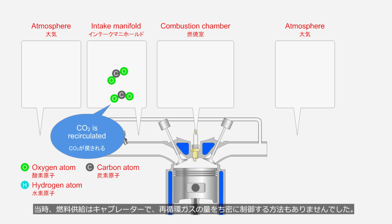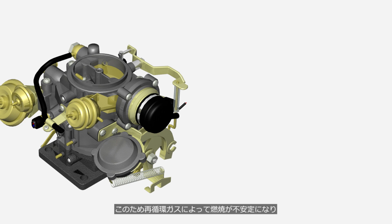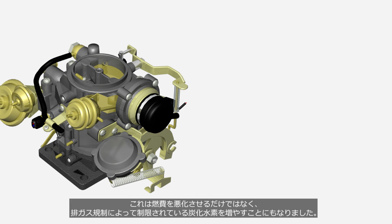At that time, fuel supply was controlled by a carburetor, and there was no method to precisely control the amount of recirculated gas. As a result, the recirculated gas caused unstable combustion. And to prevent this, it was necessary to use a richer fuel. This not only worsened fuel efficiency, but also led to an increase in hydrocarbons, which were restricted by emission regulations.